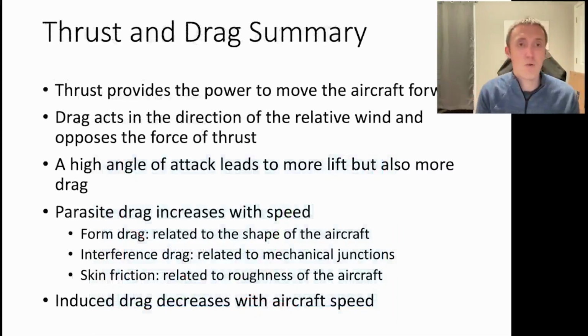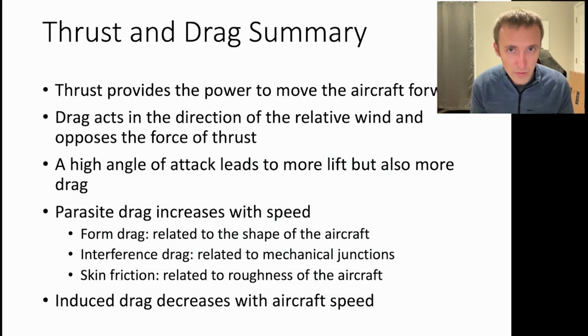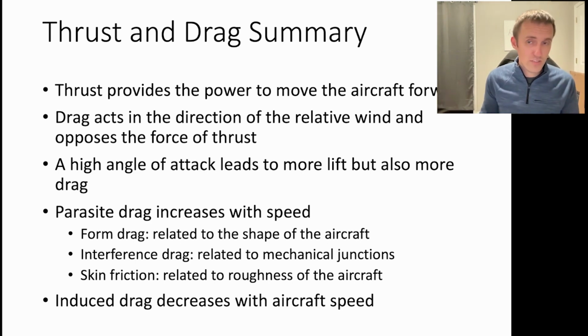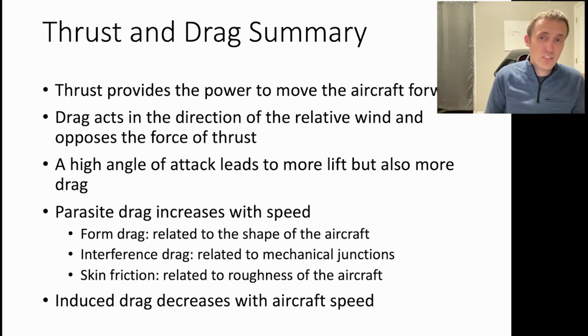So let's just summarize what we've said so far. Thrust provides the power to move the aircraft forward. Drag acts in the direction of the relative wind and opposes the force of thrust. A high angle of attack leads to more lift. I think I mentioned that in one of the other videos. A high angle of attack does give you more lift, but it also gives you more drag.